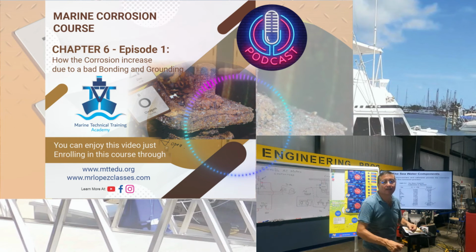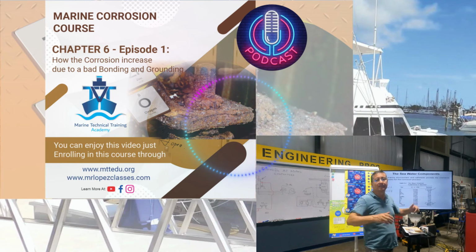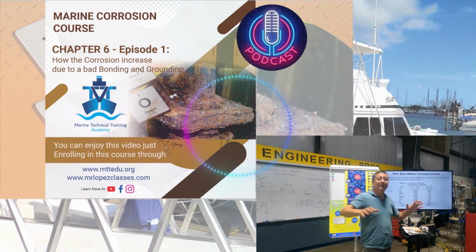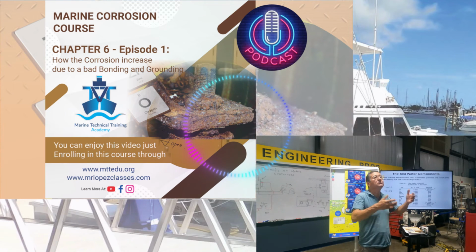If the galvanic isolator is not working, it's basically because you have too much corrosion inside of your boat. It's because the corrosion destroyed all the metals. Remember, all the metals inside of the boat shall be connected to the bonding system.